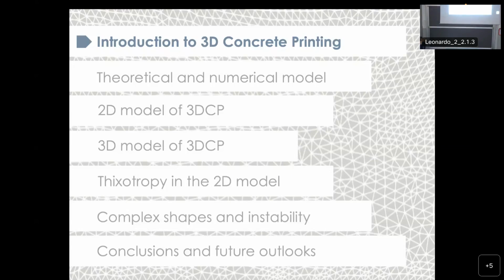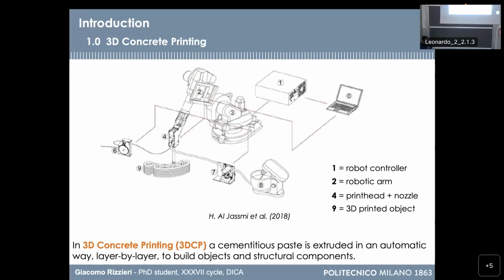of this new technology. So, in 3D concrete printing, generally there is a robotic arm or a gantry system which is used to govern a robotic control nozzle which moves and is used to extrude a cementitious mortar in order to create objects layer after layer. So there are many advantages linked to these technologies, and I want to present them to you a little bit by showing a few projects that I like about 3D concrete printing.